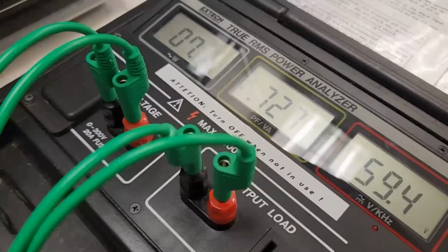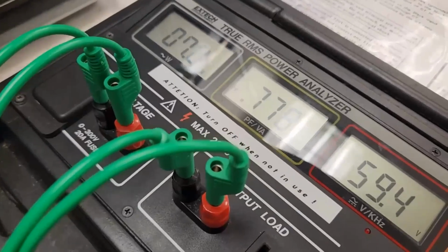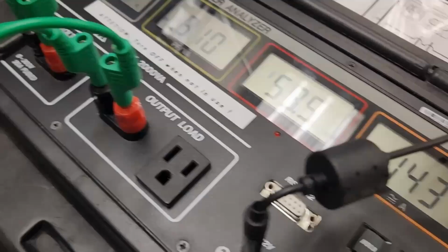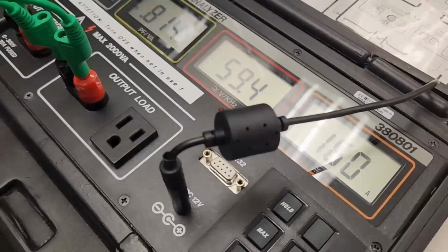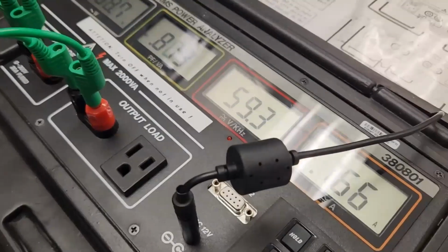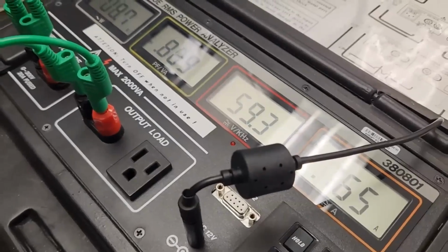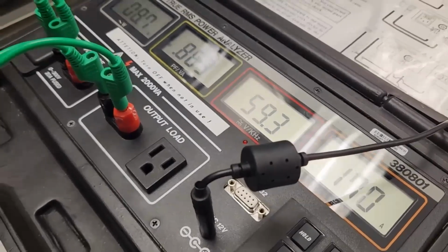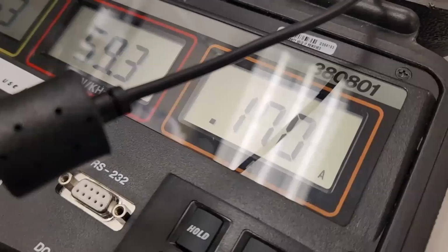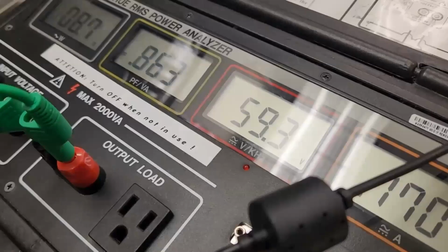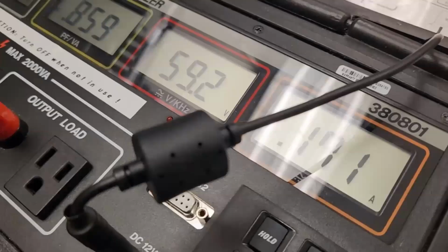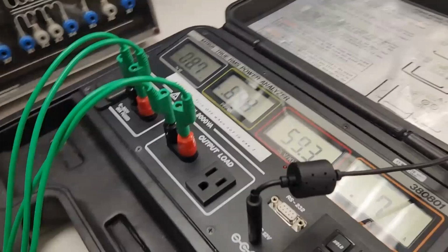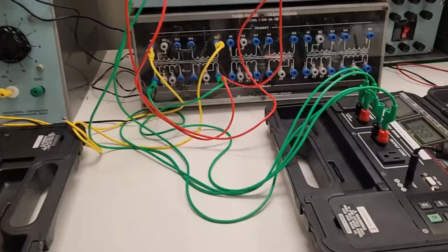So the power factor went down a little because we reduced the amount of resistance. So now let's pull it up. The power factor is now 0.8 and the current is now 0.167, which is close to... okay, that's about it. So the current is 0.17, or 0.171, and the power factor is 0.858. That's good. So now I'm happy with the circuit arrangement.